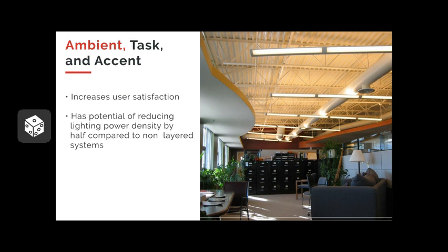If you start using ambient lighting that is indirectly lit and filling the space with light, mostly the ceiling, then you've got this beautiful arrangement, and it can even be an eclectic design up above as long as the ceiling is lighted. This particular type of lighting system can use very, very little energy because you're not trying to get the light all the way down to the floor.